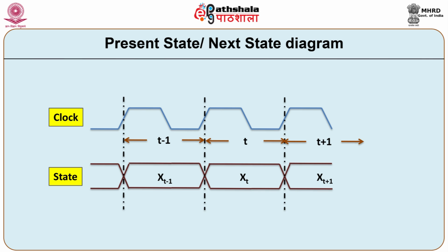To study sequential circuit, it is necessary to know the internal state or condition of the circuit. Flip flops, counters, shift registers are sequential logic circuits. All these circuits follow a sequence of internal states. The sequence of internal states is produced by a sequence of inputs. Each of the input state is characterized by a set of allowable successive states. The input condition determines which of these allowable successive states are generated next.